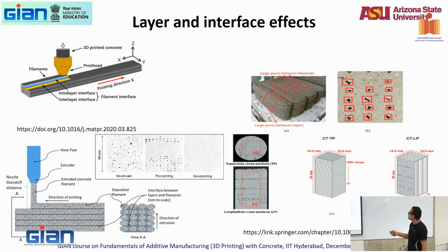Now, if you actually do it, this is what you will see: these are all the interfilamental defects. You see all of them, all of these defects where this filament joins this filament here. So there's one layer, one layer, one layer. All of this, in between all of that, are the interfilamental joints. And then in the layers by themselves, you may have voids as well.